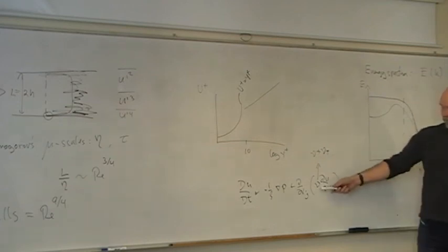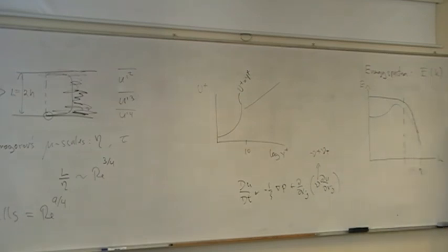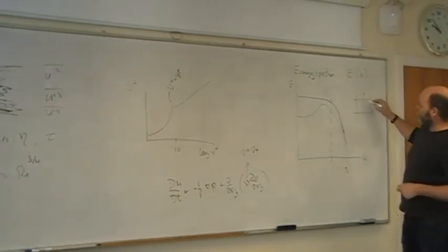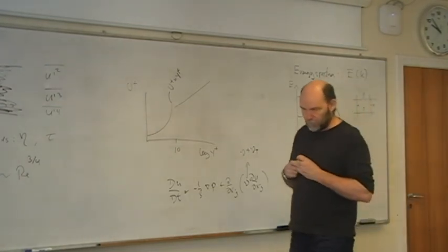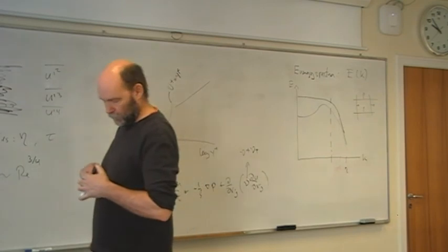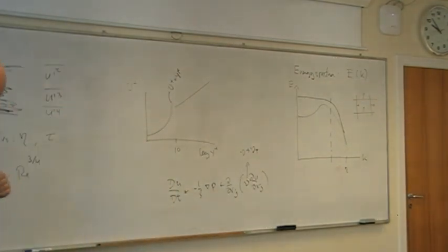Just don't, if you multiply it with 1,000, as I said earlier, that's also a turbulence model, it's just a very bad one. The turbulence model for large eddy, normally it's Smagorinsky and so on, it's more simple models, because they just look at the smaller scales. How, I mean, if you do a really bad LES, so that you basically apply this simple model to a big part of your energy spectra.